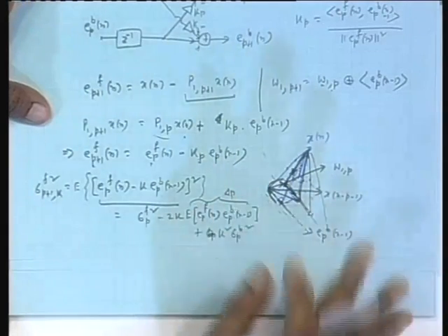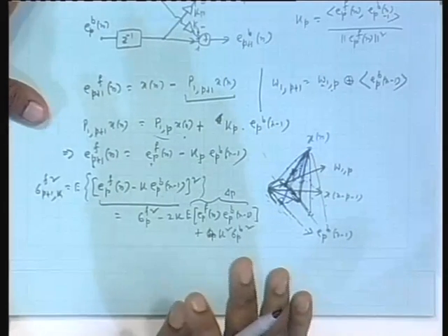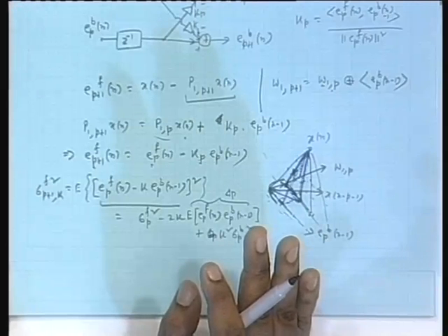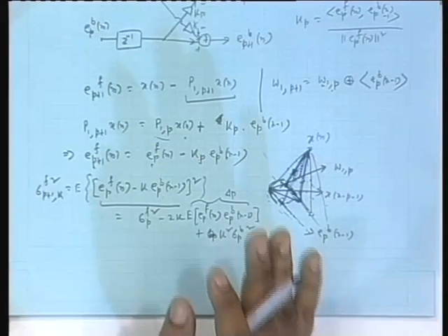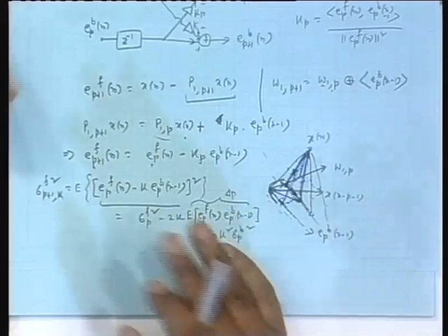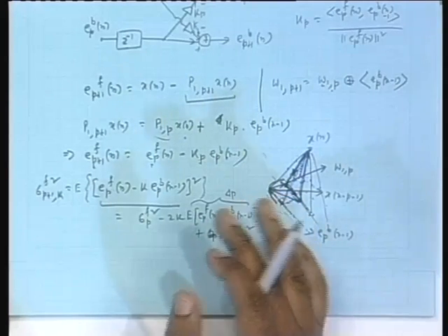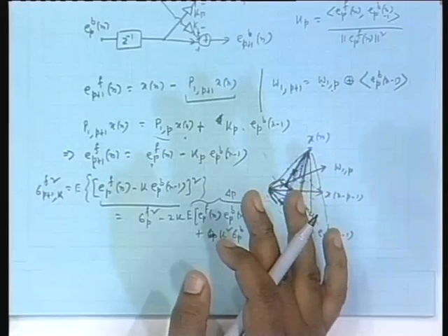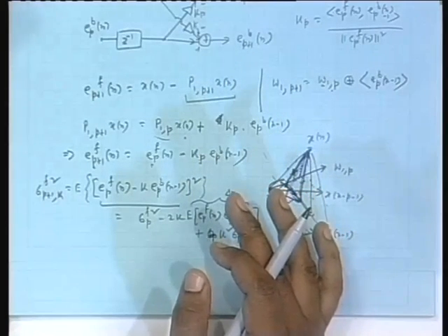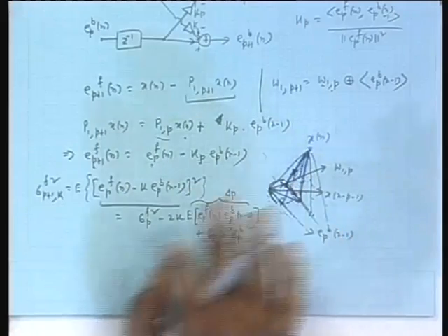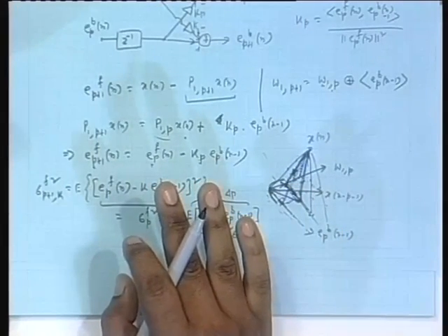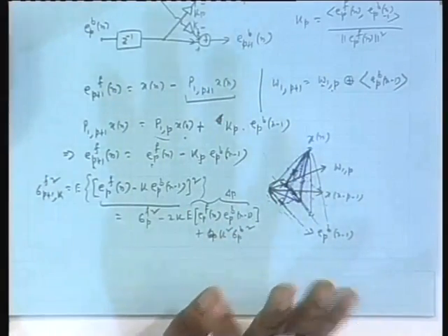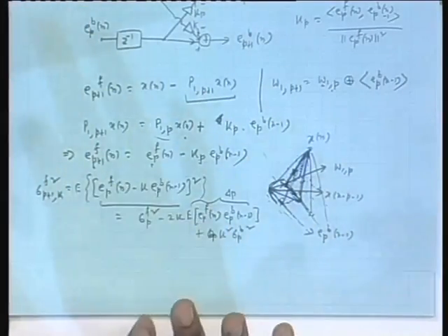I am assuming stationary process and all that for the time being, because when I moved to steepest descent from the optimal filter, I did not throw away stationarity, I assumed stationarity. That is, the gradient expression came there, R matrix was there, P was there. Afterwards, when I switched to LMS, I approximated R by a very wild approximation, xn vector into its transpose, no averaging and all that. P vector was approximated by xn vector into dn, no averaging. But that is only when I moved to LMS from there. But up to steepest descent, the stationarity assumption was valid and my gradient was in terms of R and P. Here also, when I go to steepest descent, the stationarity assumption will be kept intact.